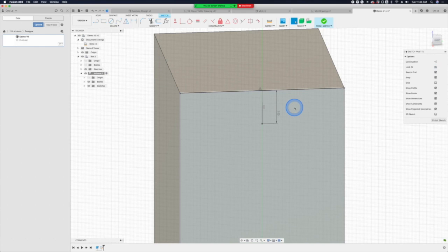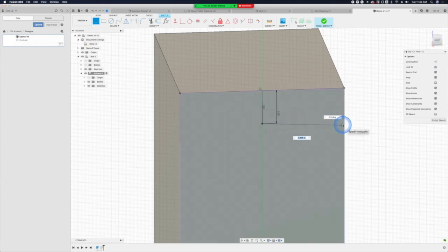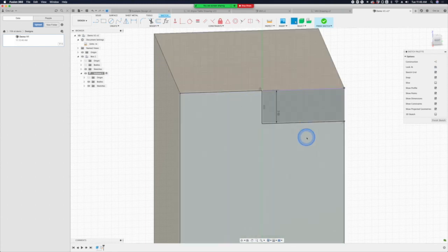Escape here, sorry. X again to toggle the construction lines. I'm going to drag this over here, snapping perpendicular to there and there. So now this is all fully constrained. And see how if I hover over this, it highlights these pieces of geometry. That tells me that they're closed shapes. So you can't extrude an open form. If one of these were a construction line, it's not closed. So this whole shape is closed, but I don't have this little corner that I want anymore.